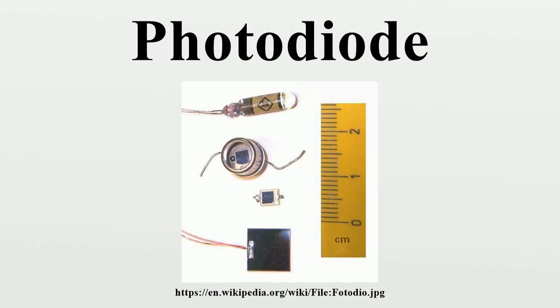The leakage current of a good PIN diode is so low that the Johnson-Nyquist noise of the load resistance in a typical circuit often dominates. Other modes of operation. Avalanche photodiodes have a similar structure to regular photodiodes, but they are operated with much higher reverse bias. This allows each photo-generated carrier to be multiplied by avalanche breakdown, resulting in internal gain within the photodiode, which increases the effective responsivity of the device.